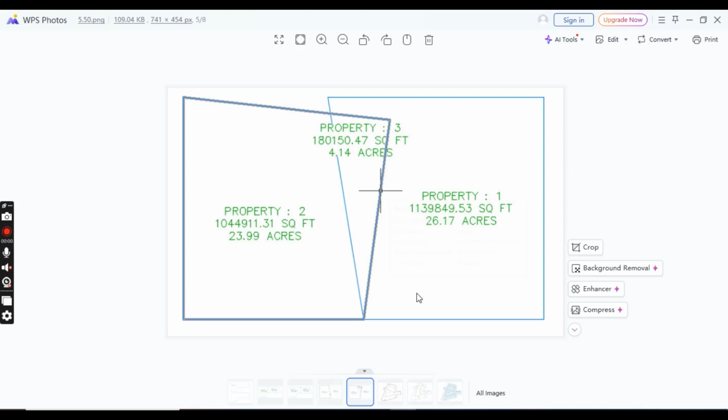Also note that a sliver parcel is formed. The duplicate site geometry object and sliver parcel make it difficult for Civil 3D to solve the site topology and can cause unexpected parcel behavior. So creating a subdivision plot of parcels this way almost guarantees that your labeling won't perform properly and could lead to inaccurate data.